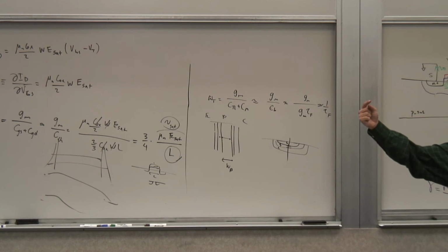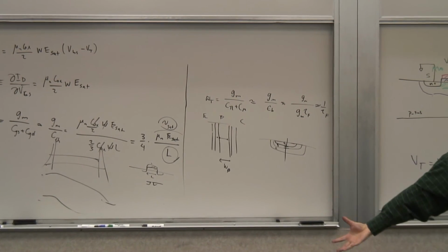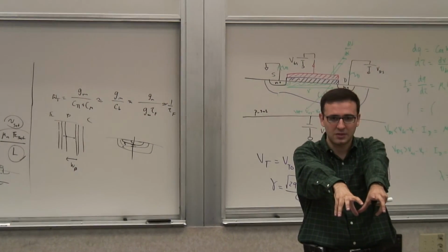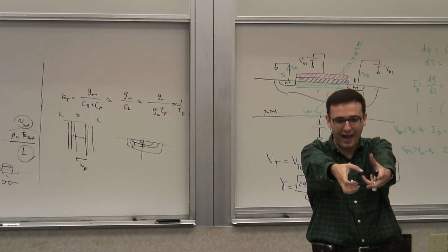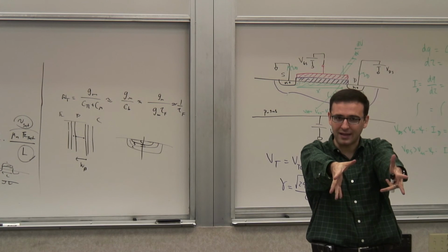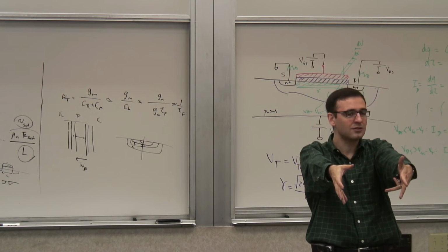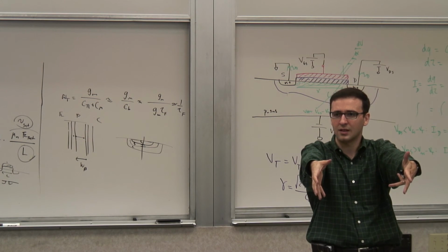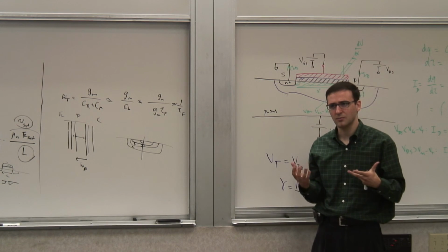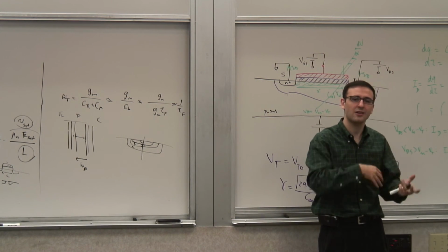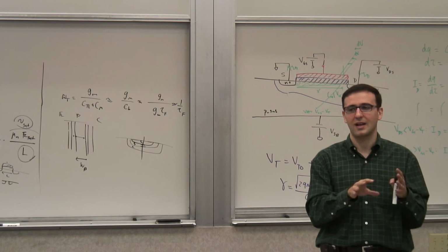And in saturation, you remember, both junctions are forward biased. So you dump a lot of minority carrier charge in the base. Now if you want to turn off this transistor, as you saw from your homework problem, you have to let this base charge dissipate. It will take time. The more base charge you have, the longer it takes to dissipate. So the bipolar gates that you can make that don't have a lot of DC consumption are extremely slow. There are all sorts of tricks that people did with TTLs and all sorts of things, but still, they are not as fast as the MOSFETs.